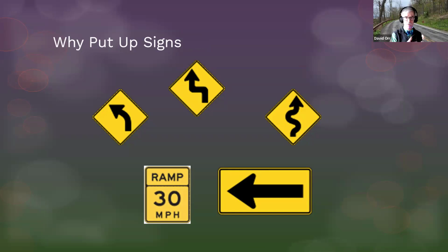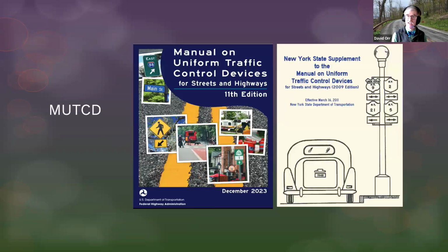This is something that people think, well, the signs are put up to tell us the safe speed to go around the corner. Actually, they're not. That sounds crazy, but they're not actually there to tell you the safe speed to go around the corner. They're there to provide uniform information to the driver. The model that's used for sign placement is based actually on driver comfort, and it's a consistency factor. In fact, it comes in the name of the sign manual. It's the manual on uniform traffic control devices, and we're providing uniform information to the driver.